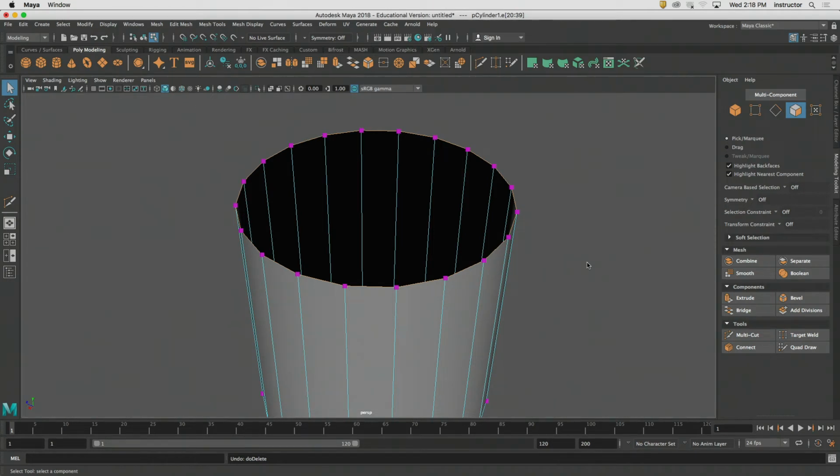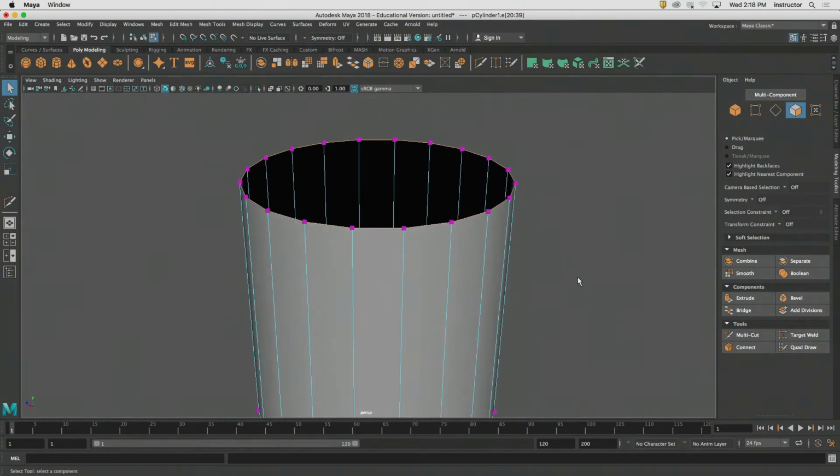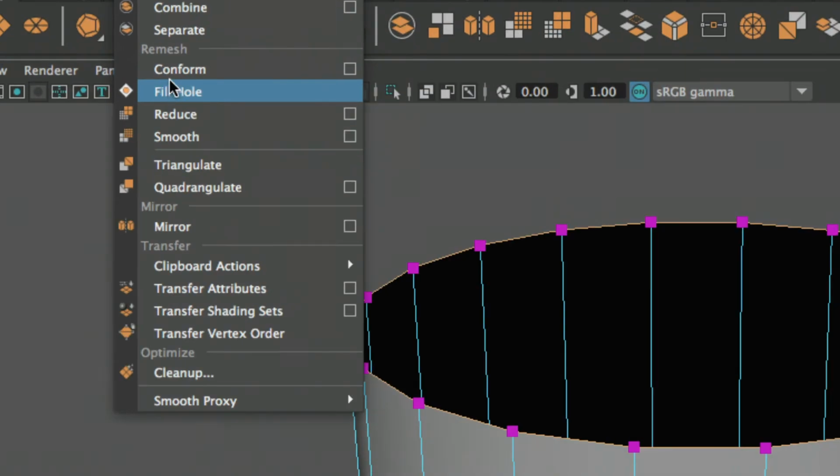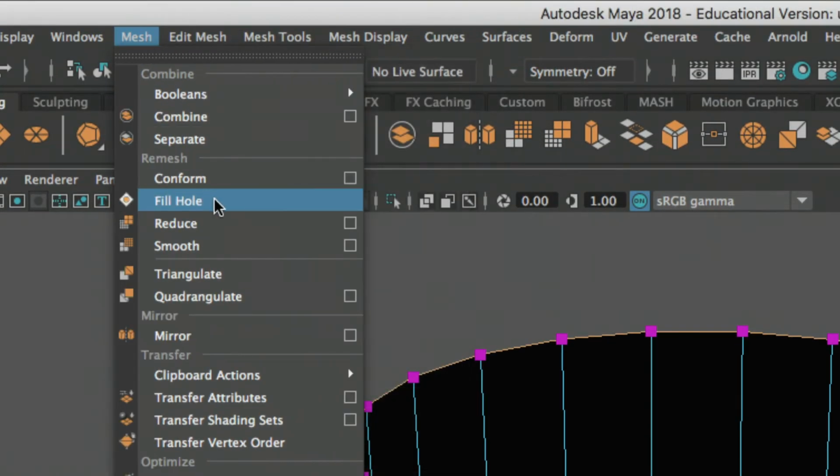Okay? Here's the 10,000 yard big picture idea. Get into the habit of doing control backspace when you're trying to delete stuff inside of Maya. Okay? It's going to solve most of your problems when it comes to editing your mesh. Now that I have a boundary edge on my model, I can fill it, okay? And that's found under the mesh tools. Fill hole.